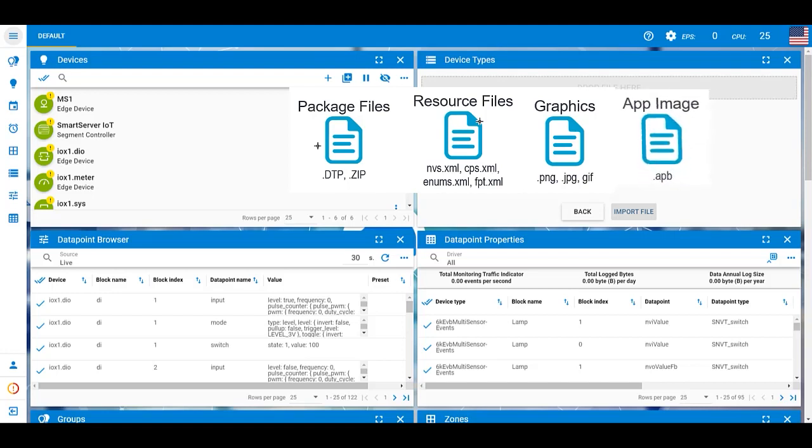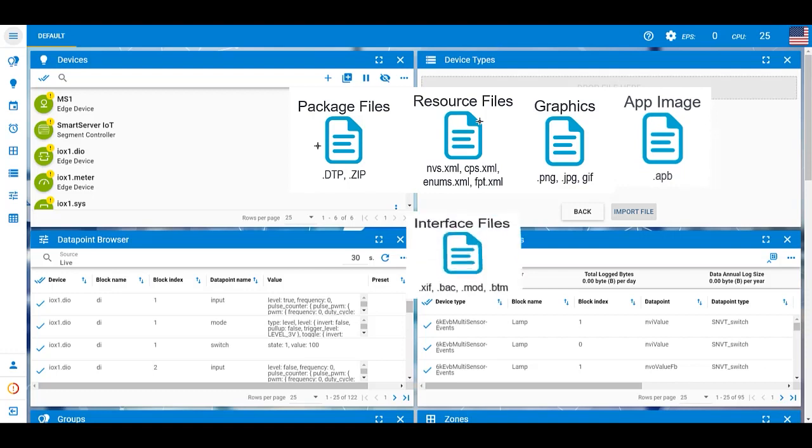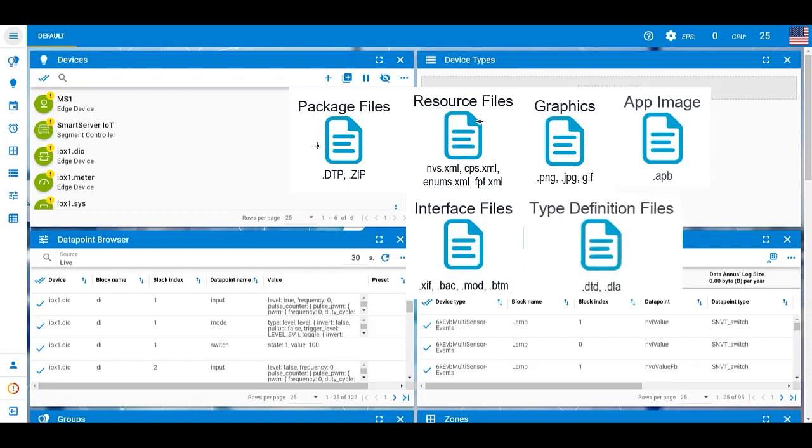APB files can be loaded. These are the application image files that can be downloaded over the network for LAN devices. External interface files include XIF files for LAN devices, mod files for Modbus devices, and .bac files and BTM files for devices that use BACnet. DTT files are used to define type definitions. DLA files define data logging, monitoring, and alarming characteristics for data points.